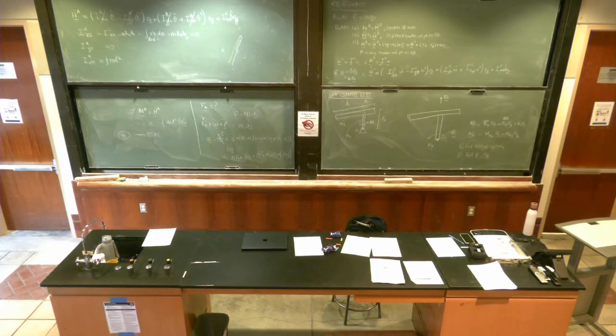How's it going? Where's your free body diagram? No, you see, it's a rigid body, so you cannot draw it as a particle. Yes, where the forces are applied matters. So you have to draw a horizontal bar, a vertical bar, and the location of the forces matter. Like one weight here, off center a little bit, weight of the vertical bar here, reaction force, reaction moment there, and then the couple applied. Okay? Draw, then let me see.